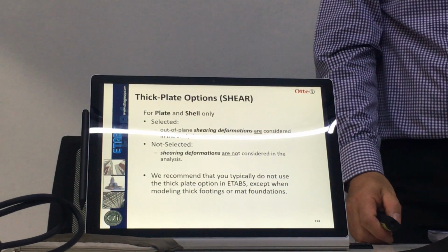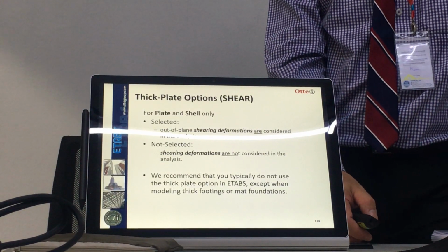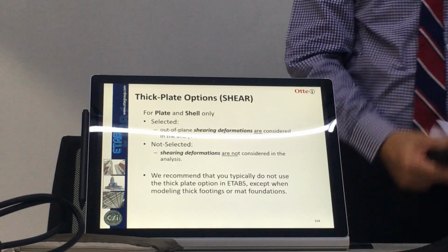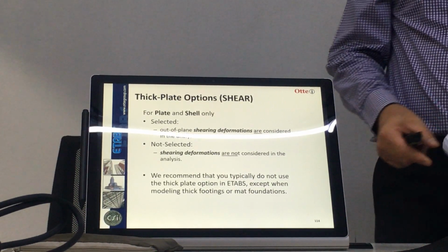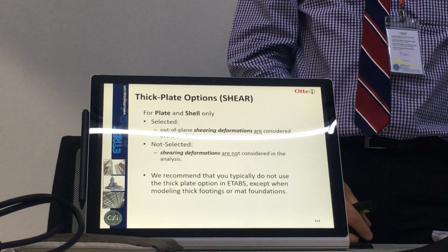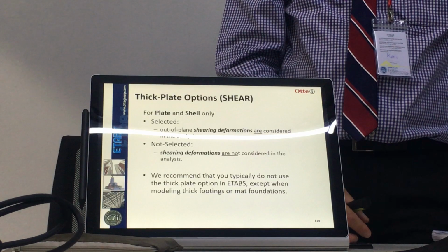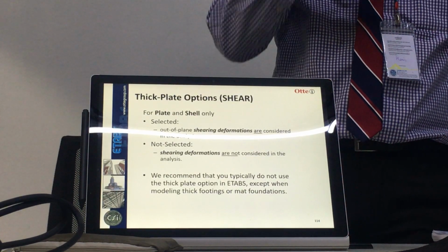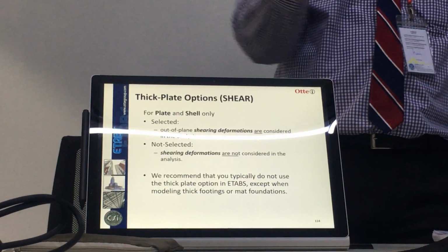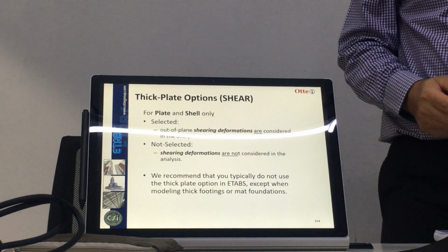And some people in the early days also used membrane for floors. Membrane has no out-of-plane stiffness, right? But a membrane floor in ETABS actually switches to another mode. It does what we call load transfer based on the virtual membrane concept, the U-line concept. Just like your deck, it's actually a membrane. You have no stiffness, but it transfers load to your supporting beam for composite beam design.